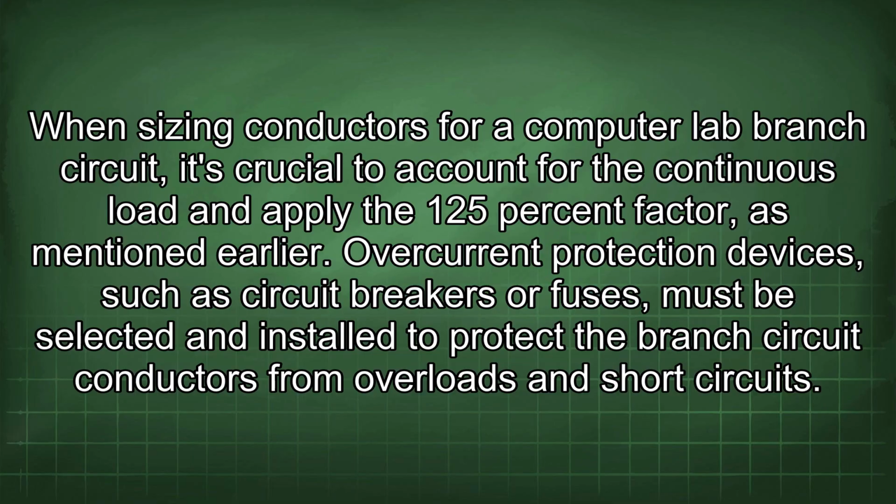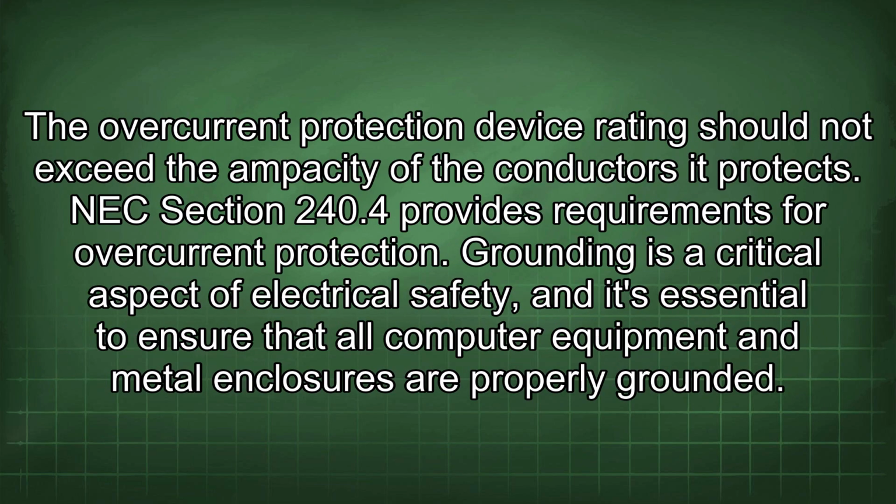Overcurrent protection devices, such as circuit breakers or fuses, must be selected and installed to protect the branch circuit conductors from overloads and short circuits. The overcurrent protection device rating should not exceed the ampacity of the conductors it protects. NEC Section 240.4 provides requirements for overcurrent protection.